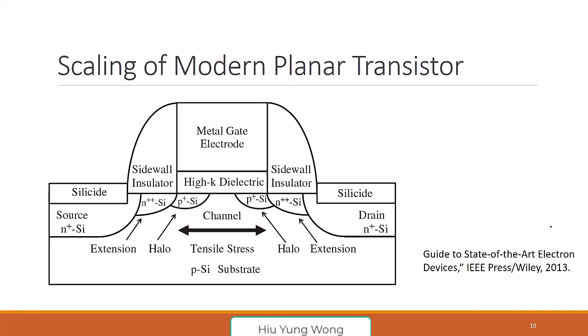You always learn a MOSFET, you have a gate, and we use polysilicon. No, nowadays we use metal gate. Why? Can someone tell me why I want to use metal instead of polysilicon? What's the difference between metal and silicon? It's more conductive. Very good. Because the resistivity rho is smaller. Why do I care about this?